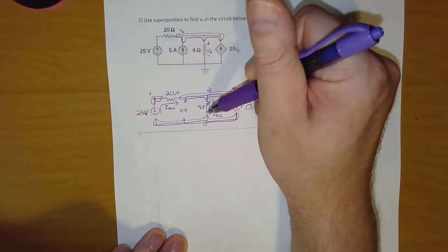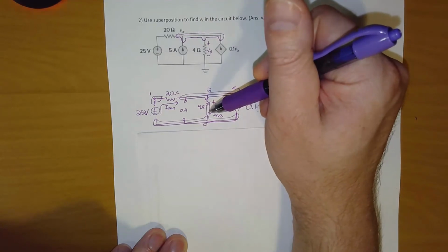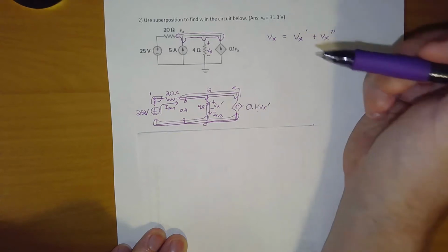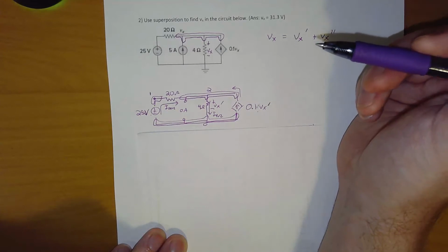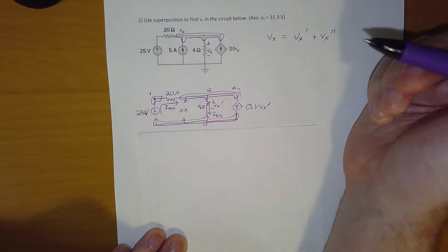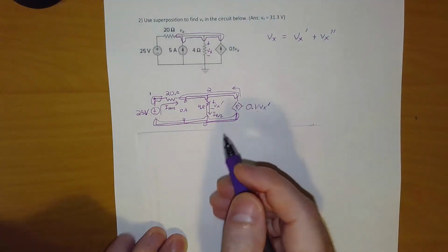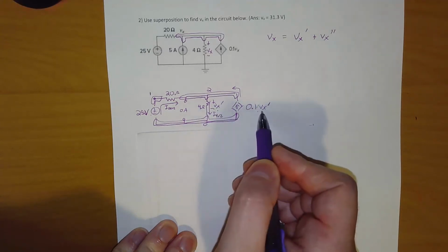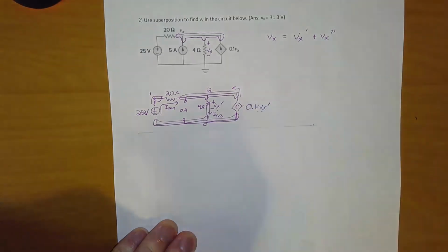Our resistors are not in series, so we can't do a voltage divider. They are also not in parallel, so I can't do a current divider. So what I'm left with is we go back to KVL and KCL, and we try to find the most convenient places to do those so we can isolate our variables. So we're going to end up with multiple equations that we're going to combine together. We also have Ohm's law. In this case, I have Vx here and I have Vx here. So note that I call this Vx prime and this Vx prime. They're not the original Vx. They're only the part of the Vx caused by the 25 volt source.